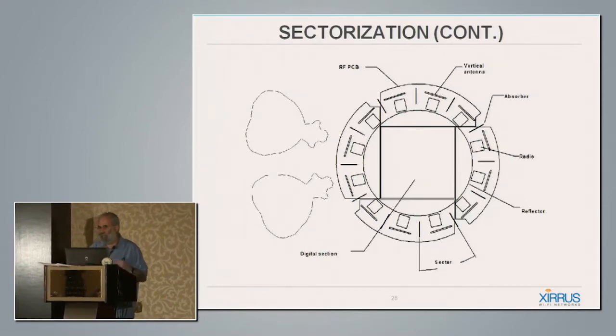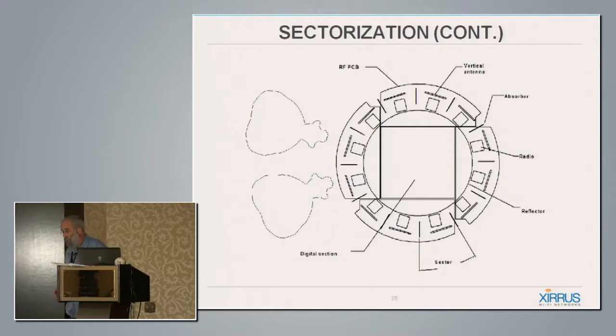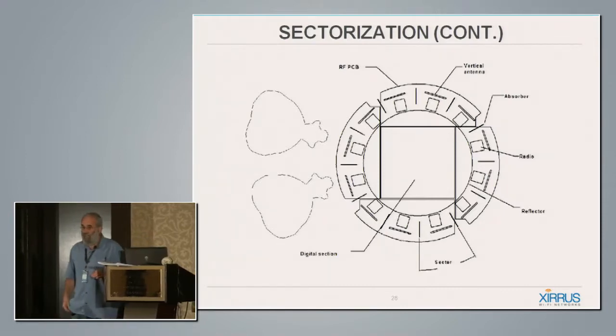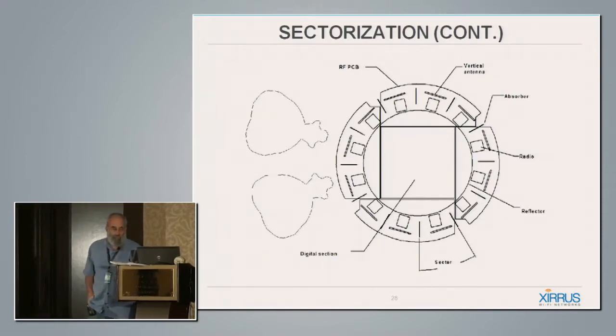I have a magic number where I want to be, and usually at 5 gigahertz, I'm trying to keep the isolation between the antennas, the physical isolation, just between the antennas, nothing to do with the radios, at about 40 dB at 5 gigahertz.